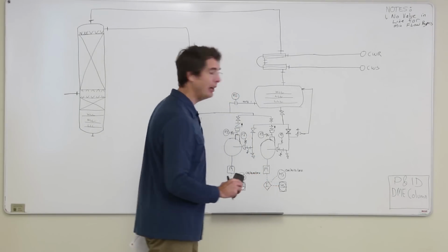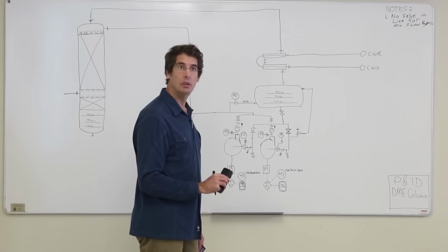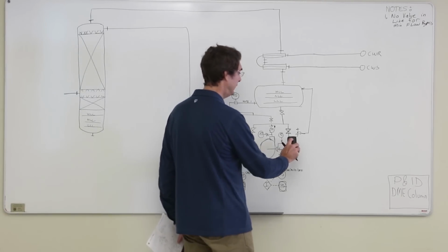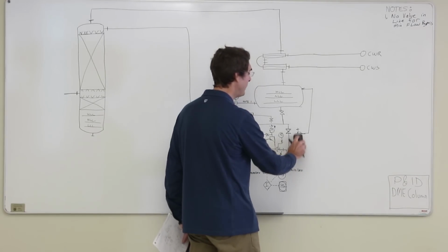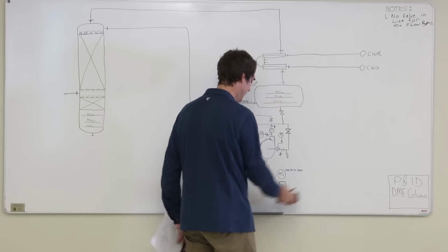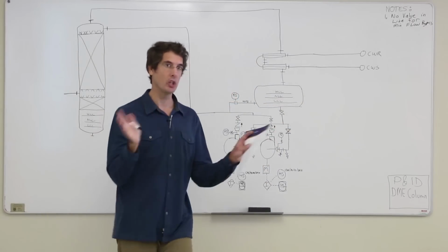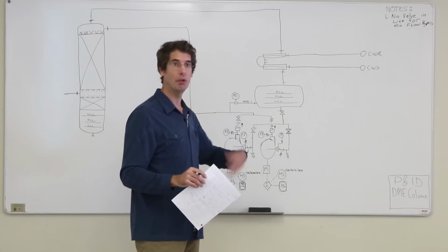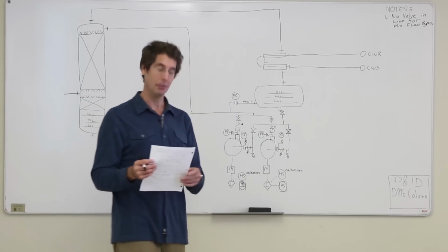It doesn't really matter where it is. Well, it would be on the discharge side that it's at high pressure, right? Okay, yeah, you're right. It depends on what the situation is that you're trying to protect. I was thinking thermal expansion. If it's thermal expansion, then it doesn't matter whether it's on the inlet or the outlet. If you're trying to protect against a positive displacement pump actually overpressuring the system, then yeah, it needs to be on the discharge, for sure.